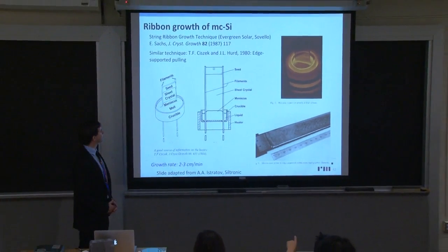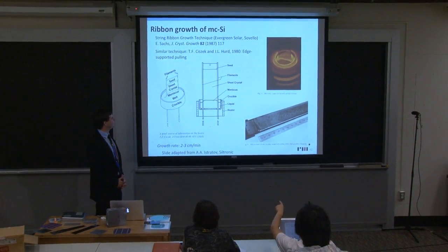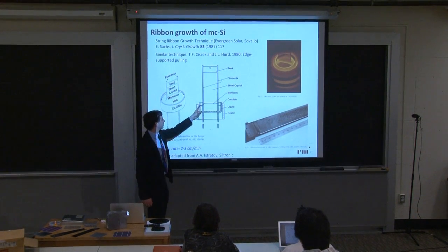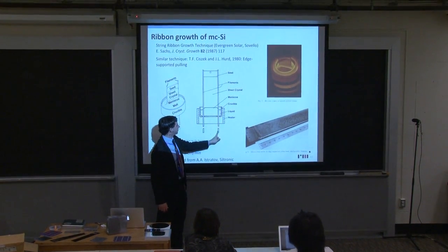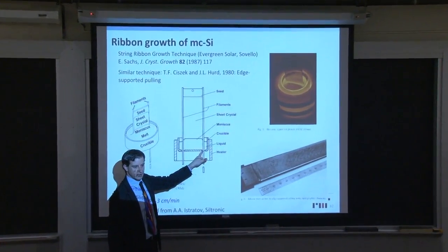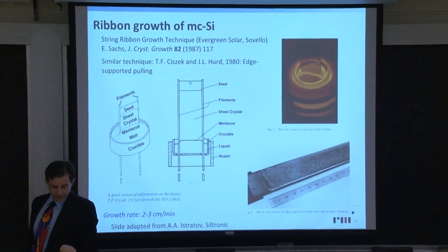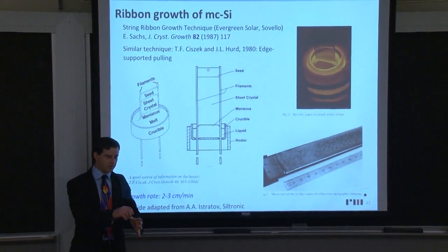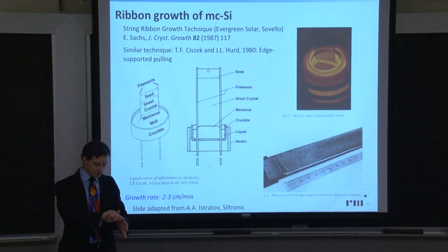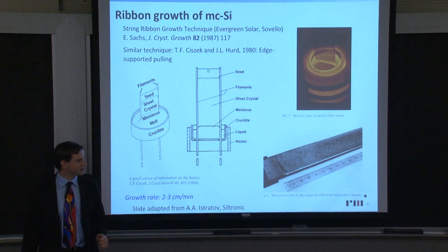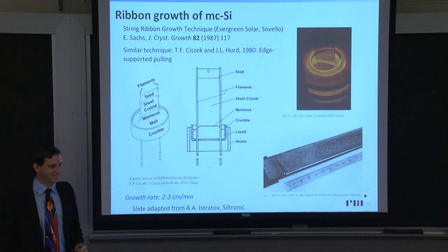Okay. How do you seal the space between the filaments and the bottom of the crucible? Right there, right? Since this is your graphite crucible right here, and these are your filaments popping up through the graphite, the beauty is you don't have to seal that. The surface tension of silicon is greater than that of water. So if you've ever filled up water to the top of a glass and seen that meniscus that forms, the silicon meniscus would be even higher than that. Oh, that's cool. Yeah, it's pretty nifty. I'm imagining this like molten metal. You don't want that spilling out the bottom. But that's really cool. Okay, cool.